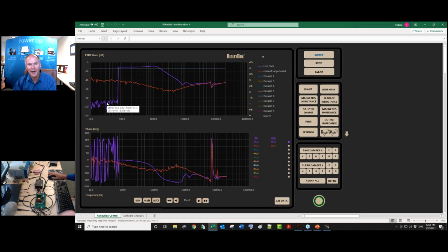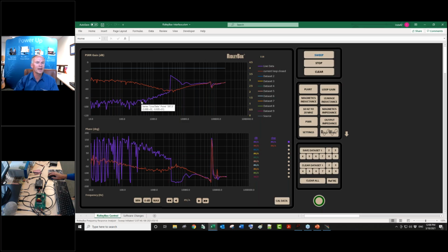And this is why, up to about 10 years ago, everybody gave up on this measurement because everybody was current mode. Okay. And then point of load came along and digital control came along and they couldn't do current mode effectively anymore. So they had to start measuring this because it was so bad in this region. And again, this is just residual noise transmission that we'd have to clean up all the grounding and everything else. But we're looking at very, very small signals here. Okay. I mean, these are less than millivolt signals coming out in the midst of lots more noise.